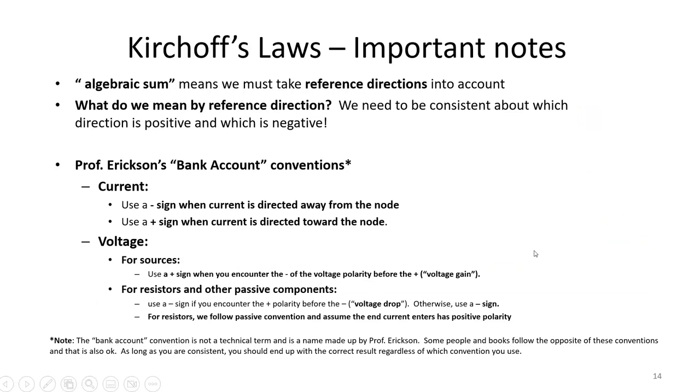Here's a few other important things to note about Kirchhoff's laws. First, notice that we say algebraic sum. Algebraic sum means we need to take directions into account. Are we dealing with a rise or a drop relative to something else? Is current entering or leaving? We need to be consistent about which direction we treat as positive and which direction we treat as negative.